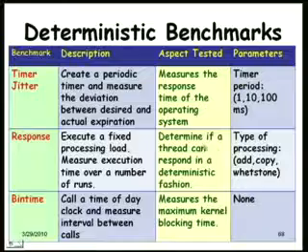The idea is that when you run a thread, will it complete in a deterministic fashion, and remember that we are considering a real time priority, the highest priority. It should not happen that the kernel is doing something internally, handling the timer response or interrupts for other tasks, and in the meantime your task is getting delayed sometimes and completing early at other times.